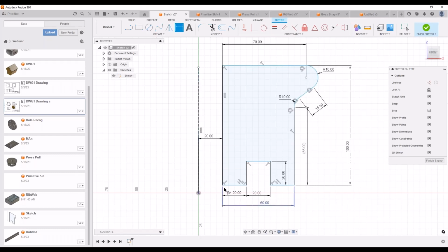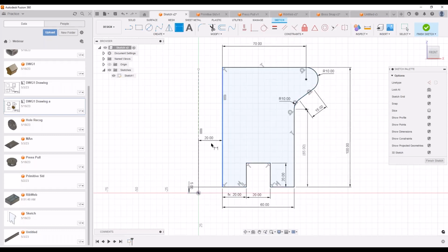I'll show you why I want to go this way. What I want to do is constrain that. Let's make it 5 millimeters away. So now the entire sketch is constrained in the space as well. So if, for example, you are doing a rotated view of something, or something that's in relation to another part, because in Fusion 360, as you know, you can do multiple solids in the same space, and you can do assemblies all in one. When you're doing that, these positional constraints and dimensional constraints start to become important with regard to your origin point, the XY 0, 0 point.